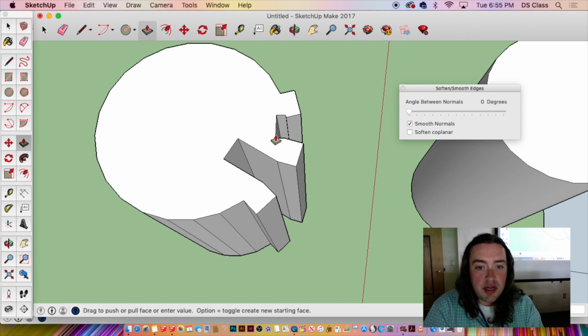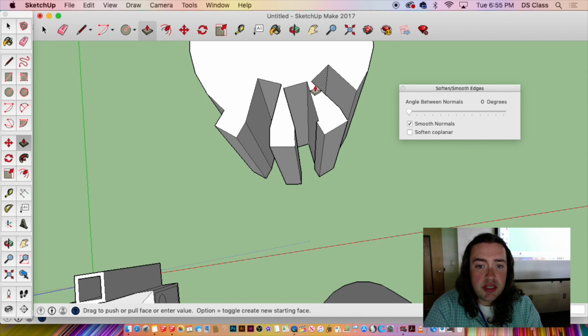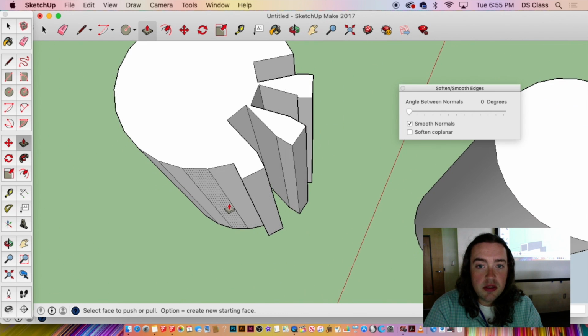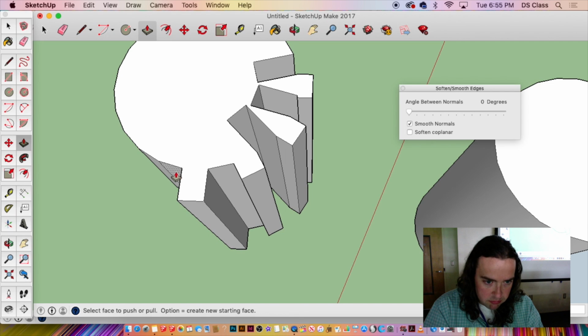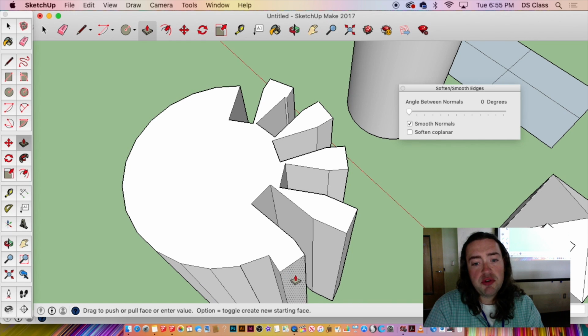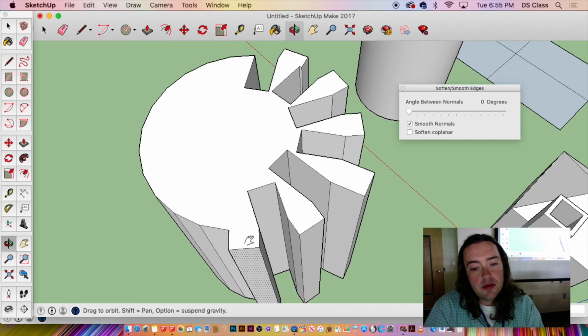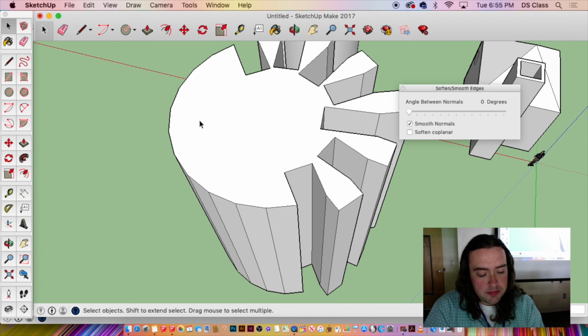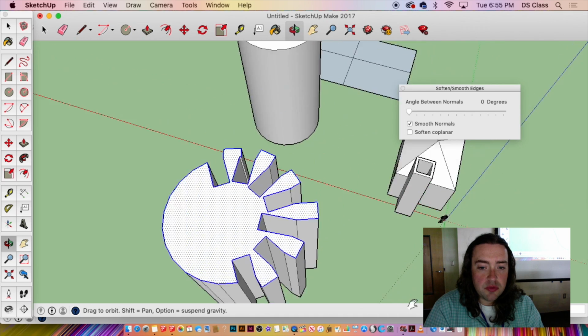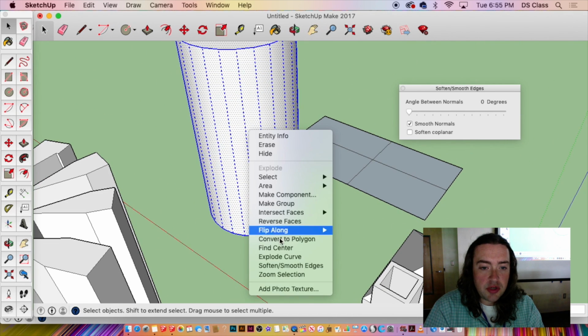I want you guys to try these. And if you get stuck, let me know, because I can't see your screens, so you have to tell me. I have circles. Oh. So if you've got the cylinder and you want to show all that hidden geometry, you triple click on it. With the select tool, not with the push-pull. So that first tool. Okay, and then once you have it selected with the triple click, it should look kind of like that right there.